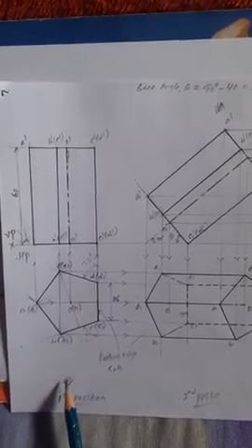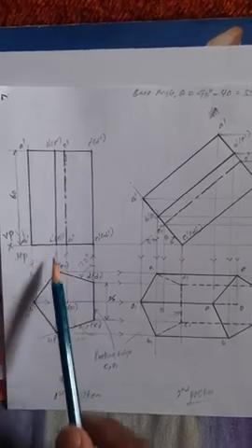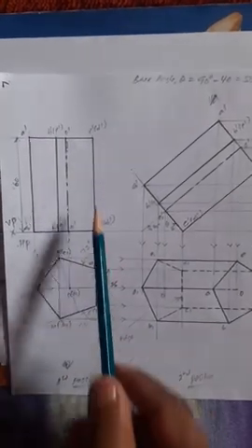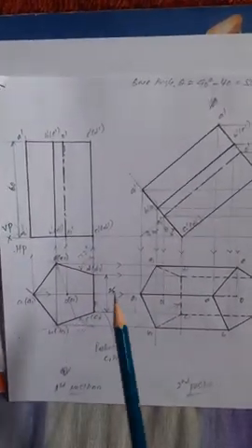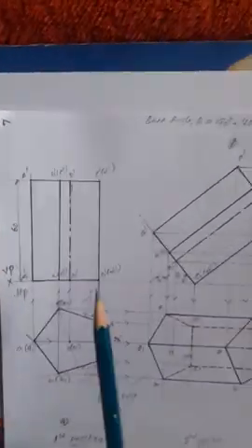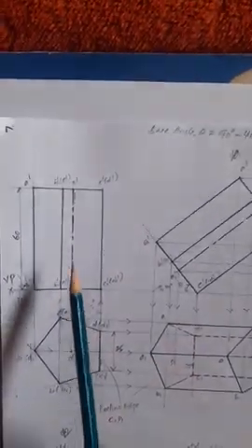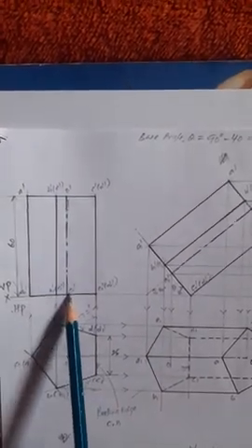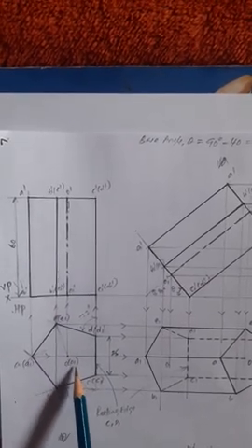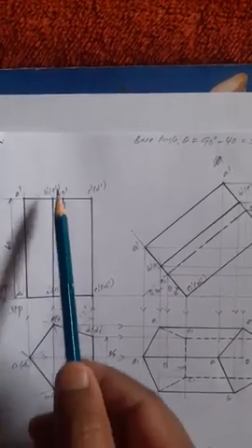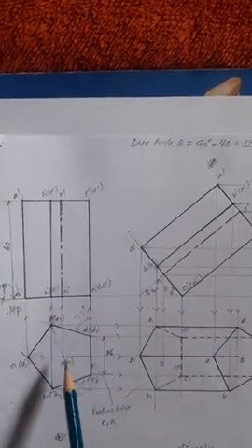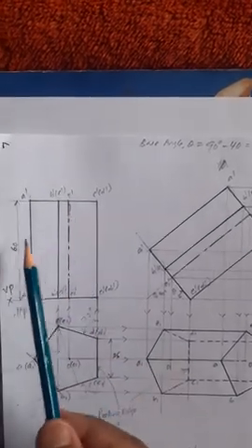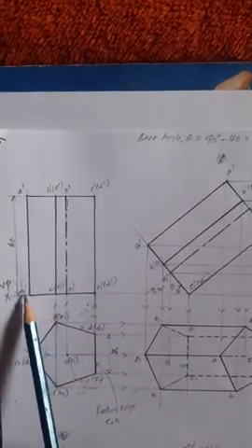When you view from the observer in front of the object, you can see the front view, right? Project all the corners of the pentagonal prism, bottom face and top face corners, vertically upward along the vertical lines. Measure the axis length given, 60 mm. O is the top face center, O1 is the bottom face center. Draw a vertical projection from each corner and the center of the base and top. Then along that line, measure 60 mm.